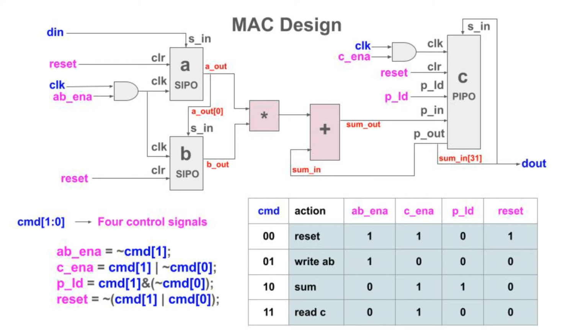When designing, it's good to use familiar and standard components such as shift registers. They are commonly used to convert between serial and parallel data. I'll create Verilog modules for a serial in, parallel out shift register and a parallel in, parallel out shift register. A and B will be stored in 2 PIPO shift register instances and C in a single PIPO instance.